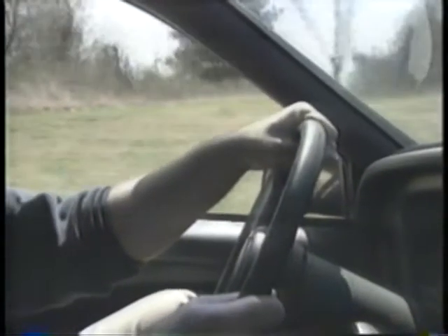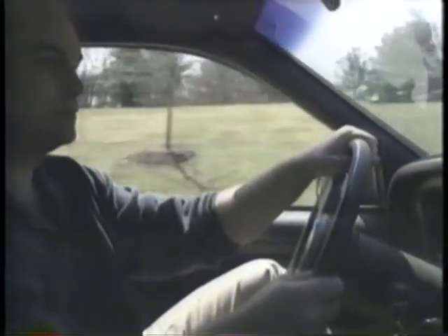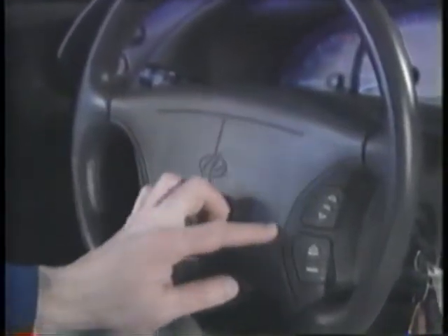Regulations mandate that in a 30-mile-per-hour frontal impact into a fixed barrier, which is equivalent to a 60-mile-per-hour impact into a parked car, the upper end of the steering column and shaft of a passenger car must not be pushed rearward more than 5 inches. There are also regulations placed on the steering wheel with regard to the amount of energy it must absorb. The steering wheel and attachments, such as the horn button, must also be constructed so that they will not snag clothing or jewelry.